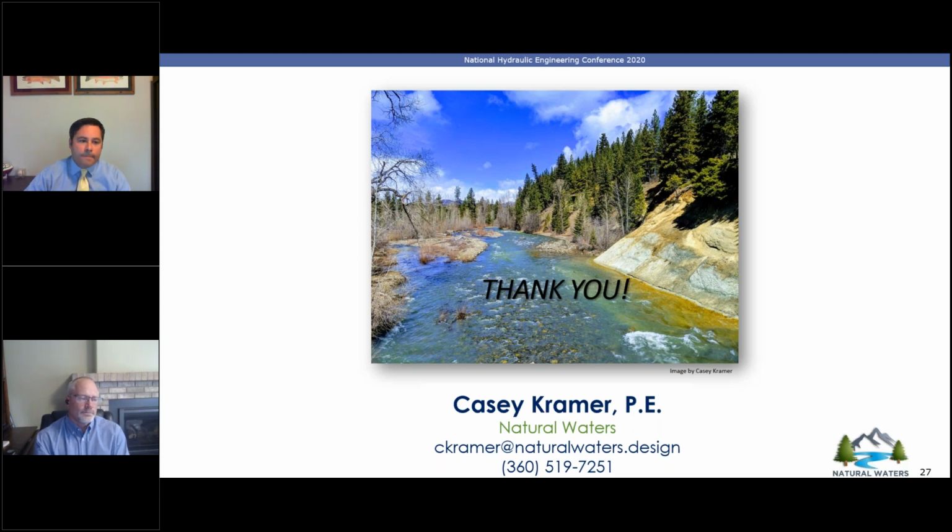Okay, another one here. Have you had to do a no-rise evaluation for multiple storm events? And if so, was it successful? I personally, for a no-rise FEMA protocol, have not had to use any flow other than the 1%. Yeah, I've also not heard of anybody having to do that either. It would be interesting if somebody has experienced that.